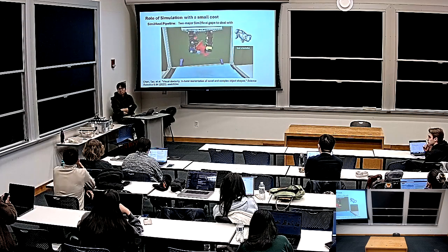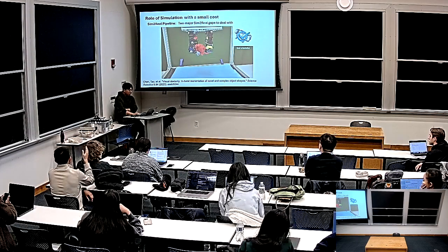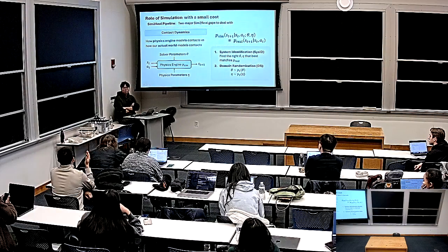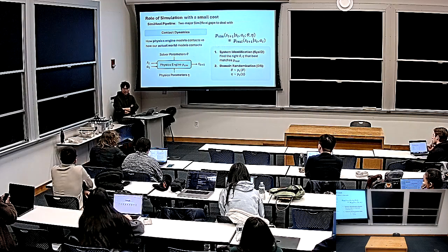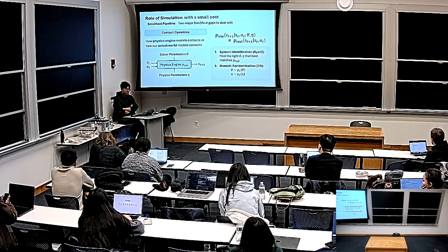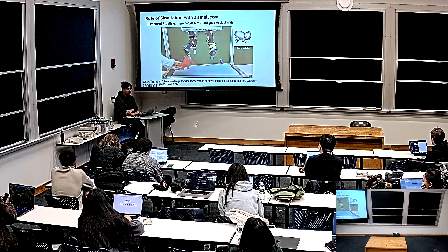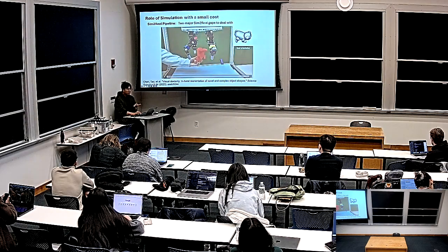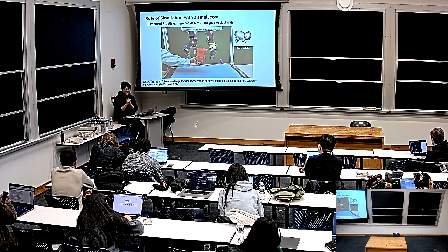For system identification, I would look at the image and look at the database and say, okay, this looks like a toy which is made of some plastic, so it should have these sorts of parameters. Yeah, it depends on the kind of task. The way we do system identification depends on the task that we want, and on the parameter that we want to infer. But in this scenario, what Tao had to infer in this video were the actual motor dynamics parameters, which is sometimes very crucial to make things work.